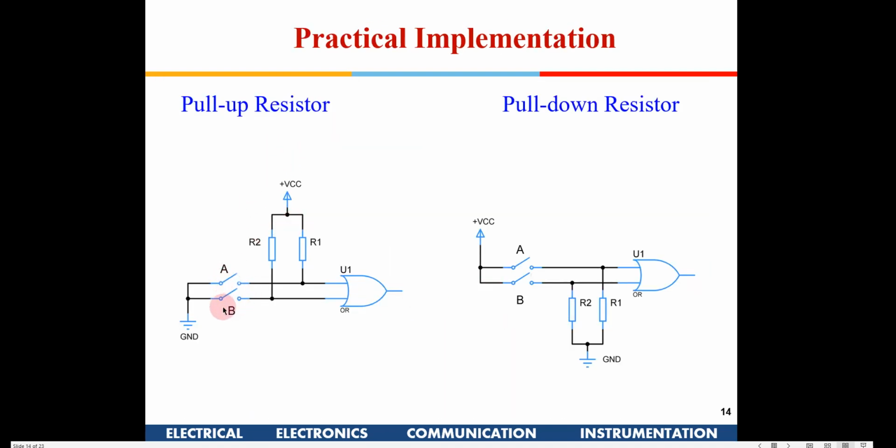But in case you have those kind of switches, which are single pole and single throw switches, you can still use them, but you need to use them in this particular configuration. So this is for an OR gate. If you see here, this is plus 5 volts, say VCC. You have connected one resistance out here, one resistance out here. This is permanently connected here. Now in this particular case, if this switch is open, what will be the input to these gates? Anybody? These switches are open.